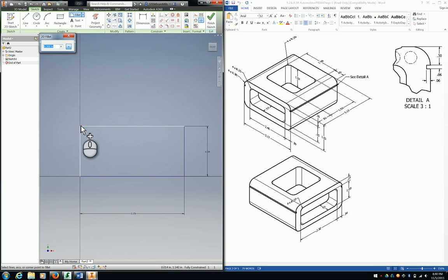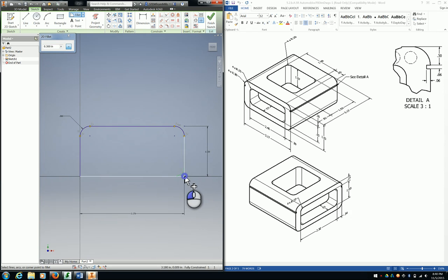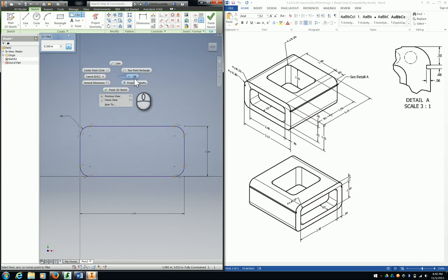Now, 2 ways I can do this. I can just click on the corner, or I can actually click on the 2 edges that are going to be curved. I kind of like going to a corner if possible. It's just 1 click, not 2. But in some cases, it's not so easy. Again, you can pause, rewind, watch that again. That was the fillet tool with a radius of 0.3 wrapped around there.